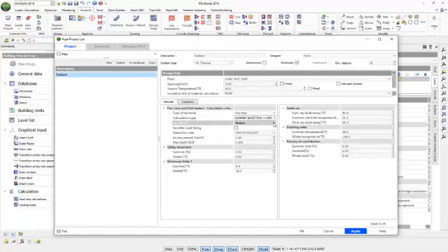Our fan speed, which we have as medium. And we also have other options such as sensible loading sizing, our water flow rate, air movement, and our max dP. Our other sections have our safety increment, which is our summer percentage and our winter percentage, our minimum delta T, summer and winter in Fahrenheit, which have been already preloaded because of our location, our intake air, our entering water, and finally our primary air contribution.